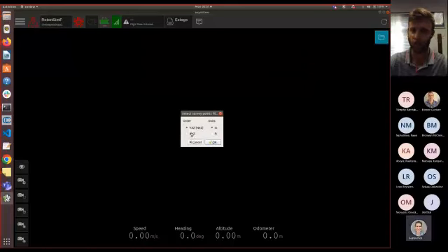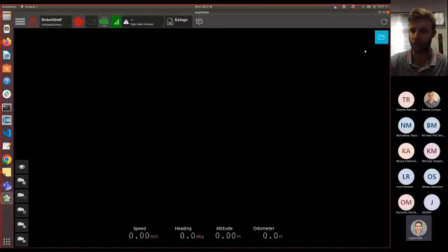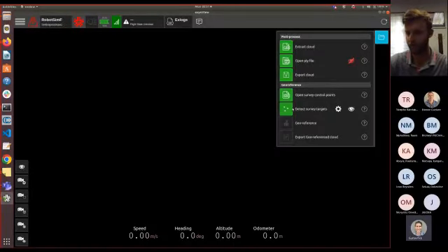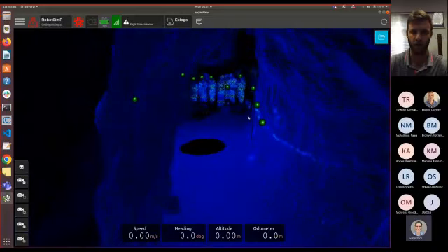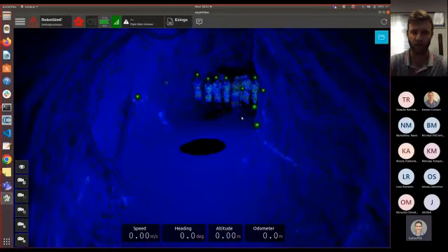I choose my order and my units. In this case, it was XYZ and meters. I'll press the OK. From here, all I do is press Detect Survey Targets. You wait a second, and once it loads in, we're going to be able to see where exactly the survey markers were and identify them and proceed with our georeferencing.